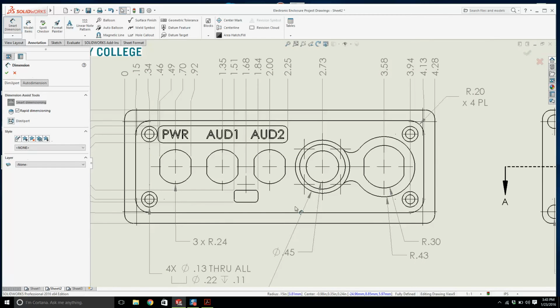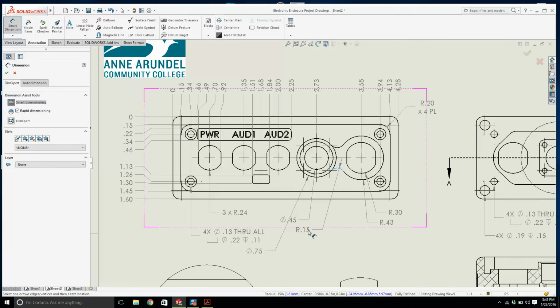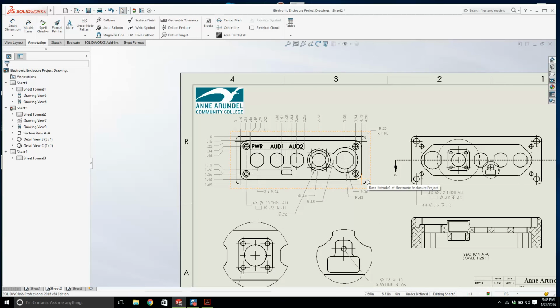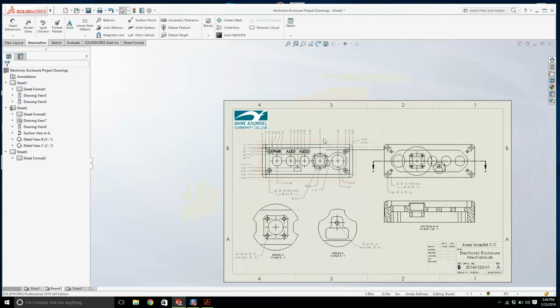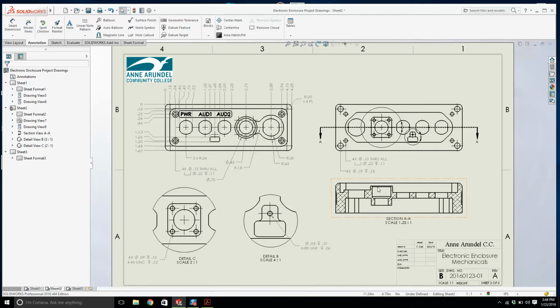So typically, you can either pretend like you're machining this part yourself, or, like what I used to do when I first started drafting, just put in a ton of dimensions, and whenever you miss something, you always got a fax back or a machinist on the phone asking what depth is that, Tim, or what size thread is going in there, or what is this fillet here, or can we make this a little bit bigger?